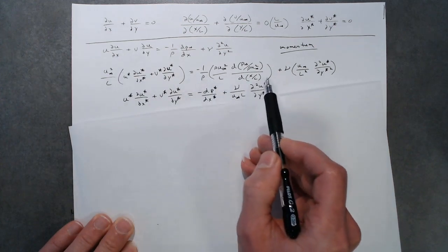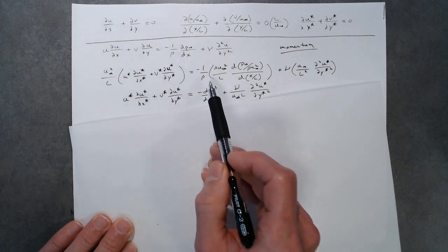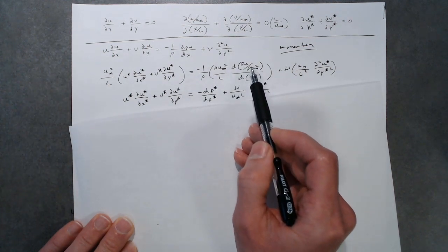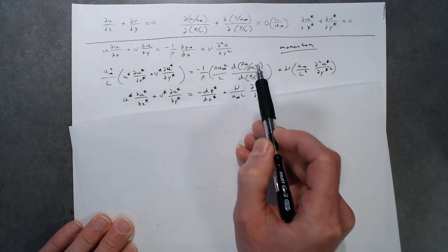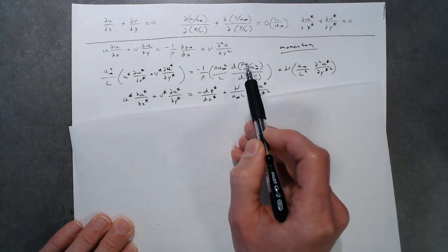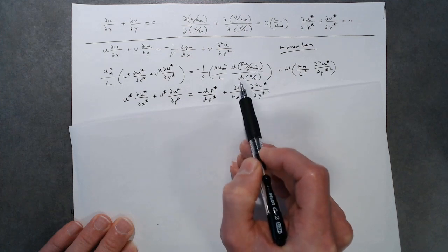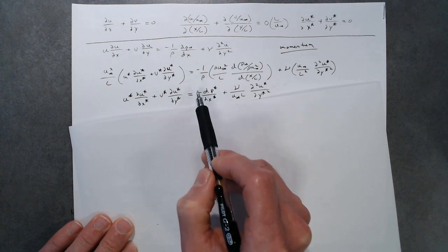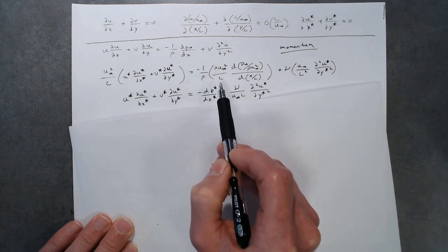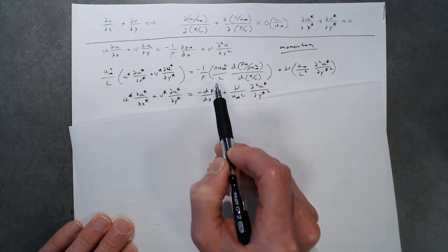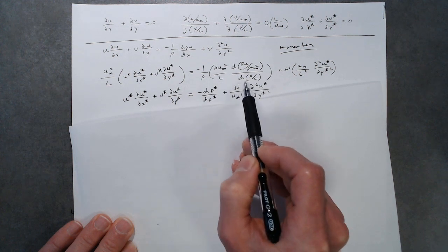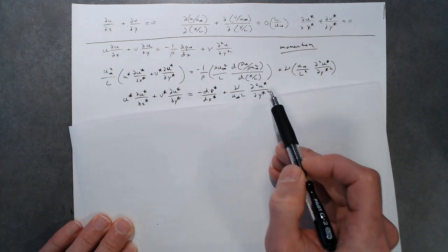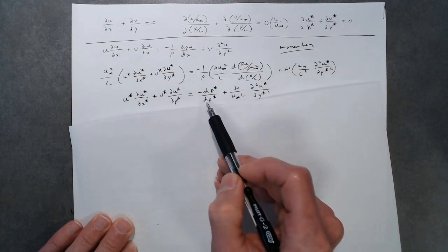Let me be a little bit more explicit in the term relating to the pressure gradient in the free stream. And we can say that if we were to divide P infinity by rho u squared, then we have to multiply by rho u squared in the numerator, this prefactor. Likewise, if we multiply by L in the denominator of this prefactor and divide x over L, then we change these into their non-dimensional forms and introduce this factor.